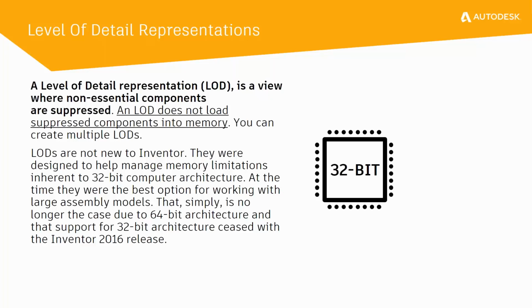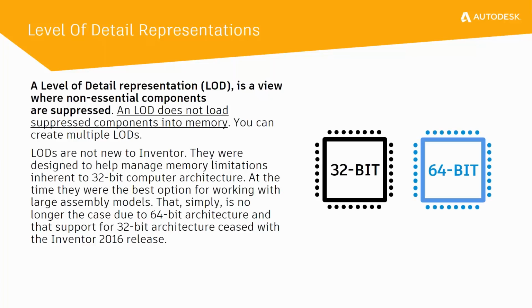At the time, it was the best way of working with large assemblies and managing the memory usage of your system. But the reality is that 64-bit systems now offer much more capability and capacity in terms of memory usage. And with Autodesk having stopped releasing a 32-bit version of Inventor since 2016, LODs have in some ways become a less critical part of the workflow when working on large assemblies.